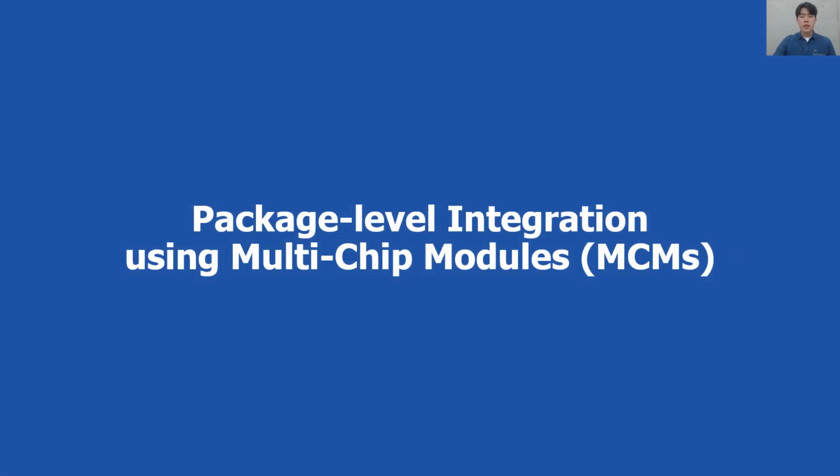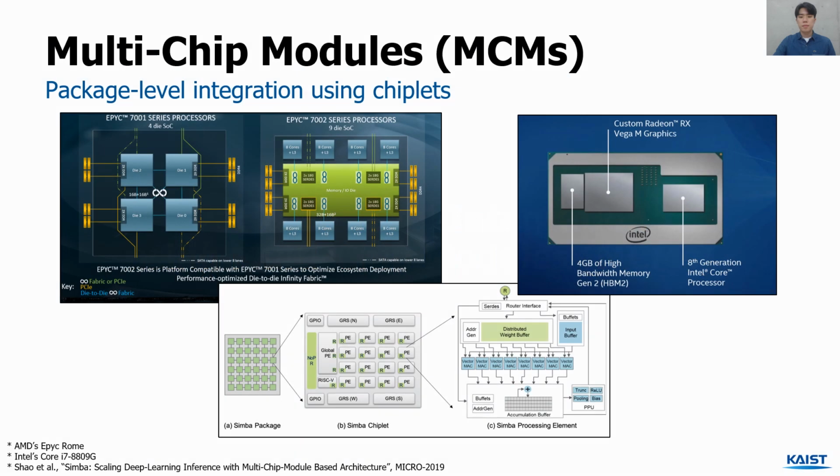To address the heterogeneous sparse and dense compute, and memory limitation of recommendations, we propose to utilize chiplet-based package-level integration technology for designing end-to-end accelerators. A chiplet is a block of integrated circuitry designed to work with other chiplets to form a larger and more complex chip. A multi-chip module, or MCM design, can connect multiple of these chiplets using a die-to-die interconnection and assemble them inside a larger monolithic package using advanced packaging technologies.